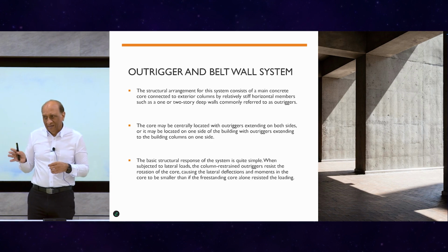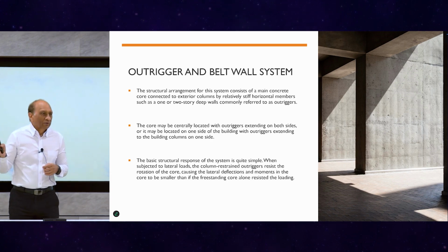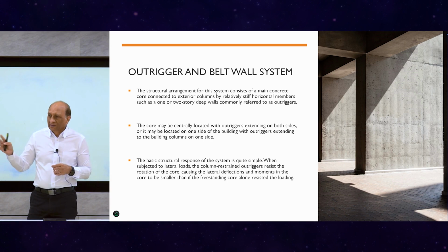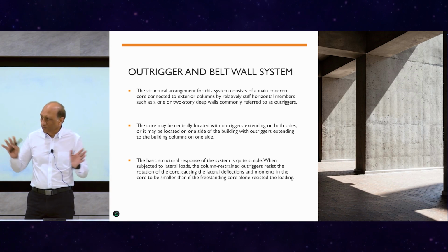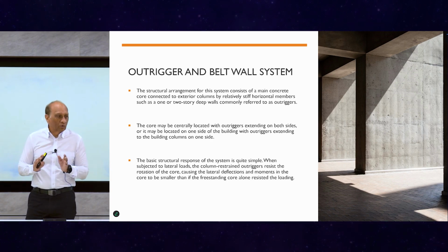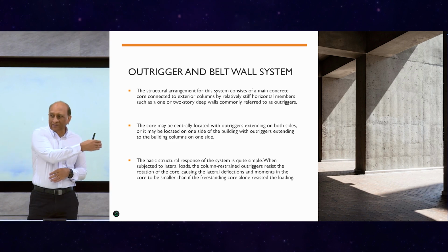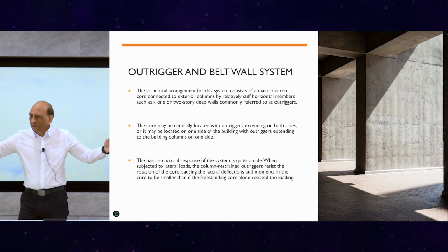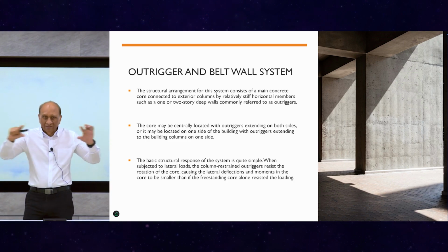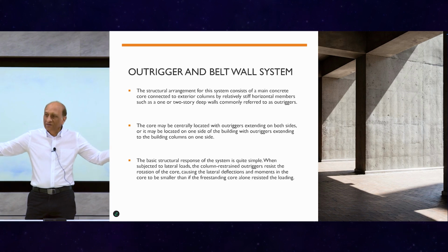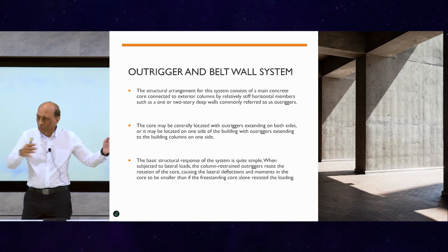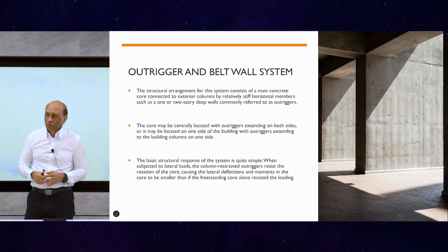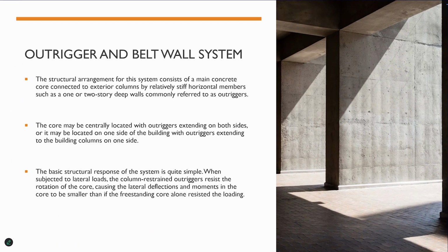They're not connected directly. So how do you follow the 4 commandments? That's the idea, to connect the outer frame with the core walls, and then through that connect to the other side. So actually one side of the frame goes to the core wall, flows through and goes to the other side. So the whole system, outer two columns, boundaries are connected to each other through the outriggers and through the core wall. So that's the idea.